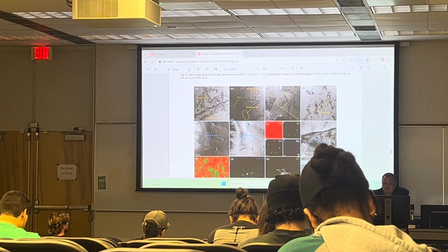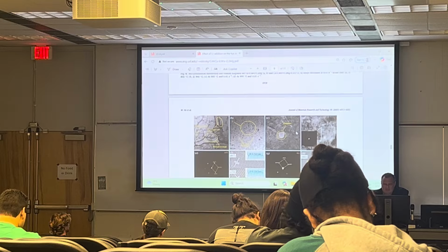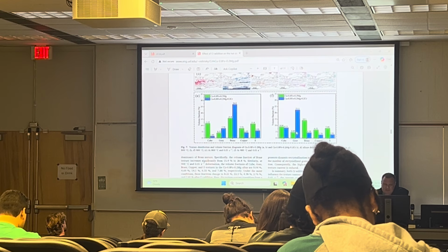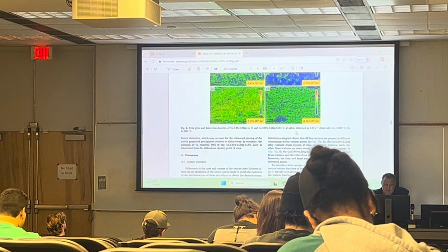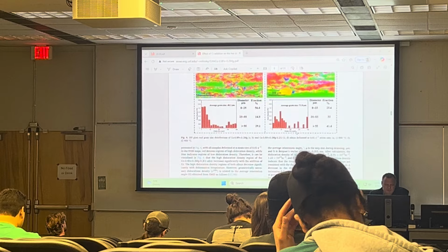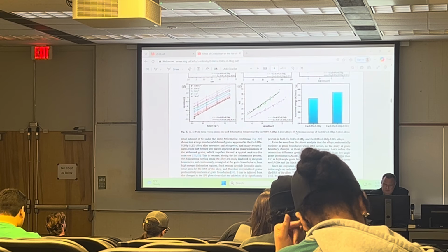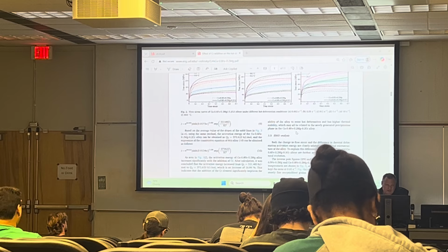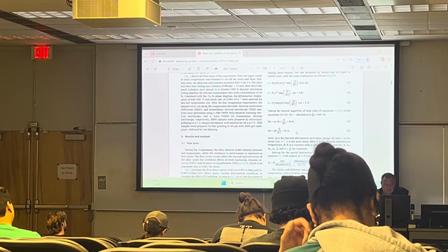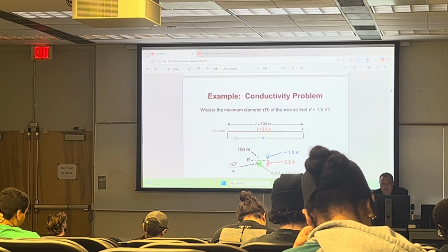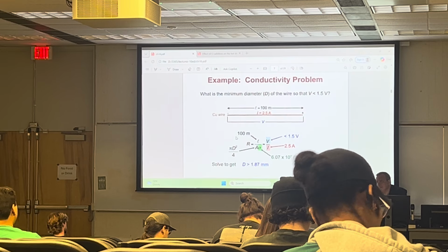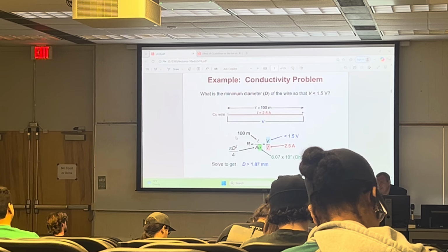To control the process, to control the structure, to control the properties. This is the structure. But everything is compared to electrical conductivity, and it's determined as a percentage of copper. So the problem with copper is that you can add a whole bunch of other stuff that's going to increase the properties, like hardness, to make it harder material, but you're going to jeopardize the strength. Okay? So we're optimizing on two parameters. One is the electrical conductivity, and the other one is the strength.